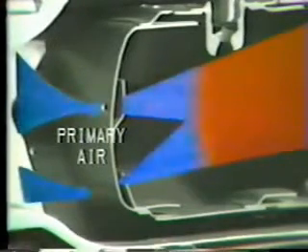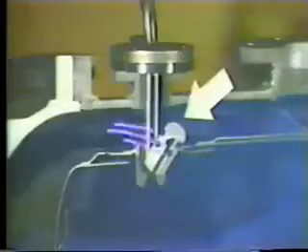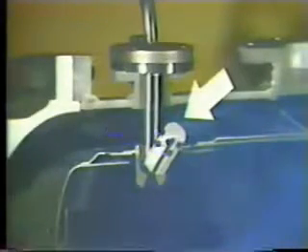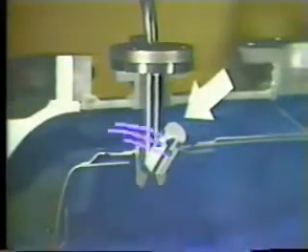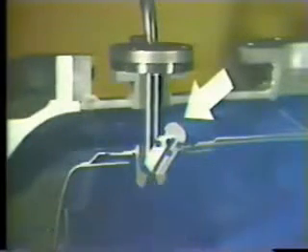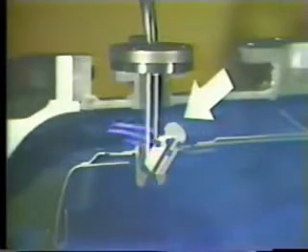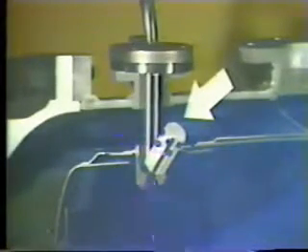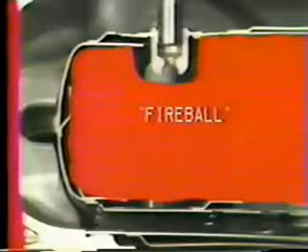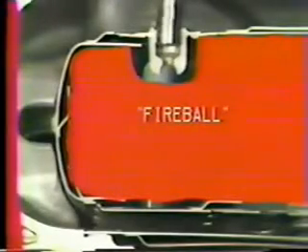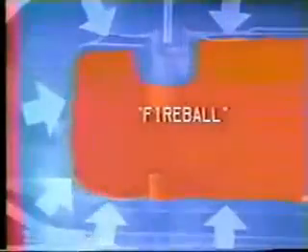Combustion uses only about 1/4 of the air available at full speed. This primary air enters the combustor through many holes in the inner and outer liners. But most of the combustion air enters through air blast tubes located adjacent to each fuel injector boss on the outer liner. Here you can see how the blast tubes are associated with a fuel injector boss.